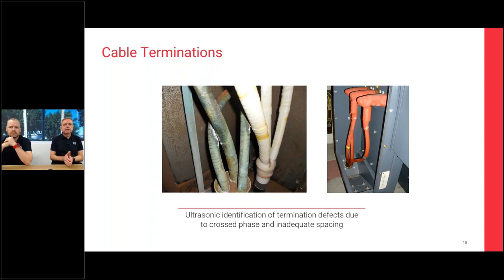Those sorts of defects are generally only found using ultrasonic techniques. It's a surface type defect, phase-to-phase discharge. You've not got a massive component to earth. The easiest and typical way of finding that is just to use ultrasonic testing at the termination box.